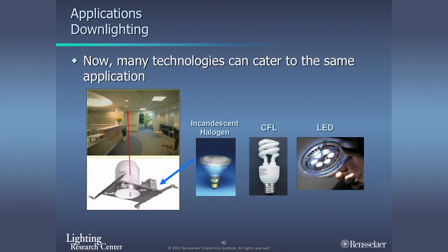When you look at CFLs, compact fluorescent lamps, which I think is what we have over our head, they're maybe 60 lumens per watt if you get a really good quality one. Now, LEDs, you can easily get even an LED replacement that's up close to 100 lumens per watt. So on efficacy alone you're saving, but it's really the optical efficiency. It's very interesting when you look at the different technologies.